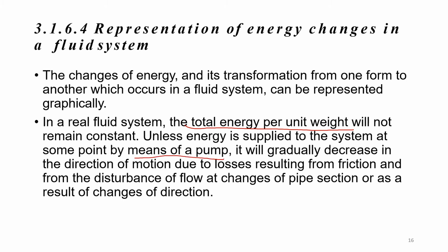Okay, energy will not remain constant unless we supply a pump. Okay, energy adding, energy gain. It will gradually decrease in the direction of motion due to losses resulting from friction and from disturbance. Okay, disturbance includes change of size of pipe and also maybe losses from the turbine, energy loss from the turbine.